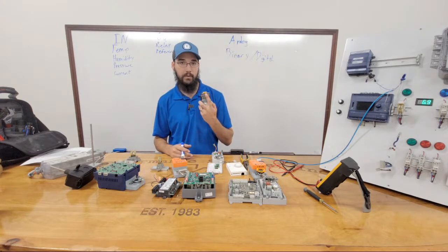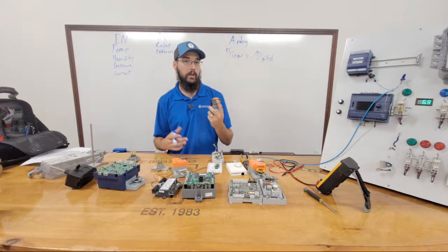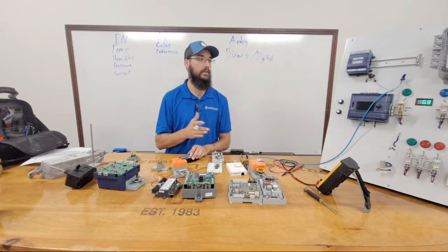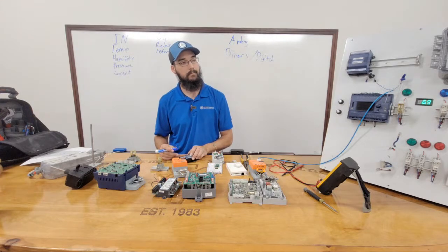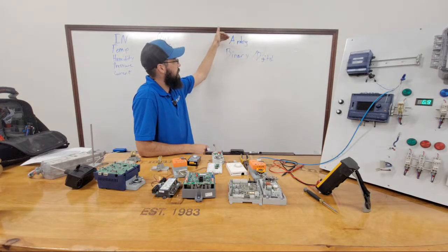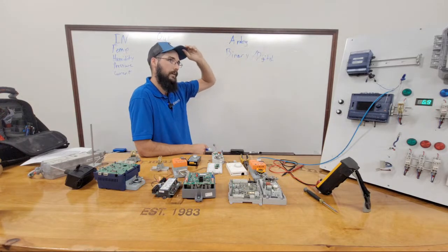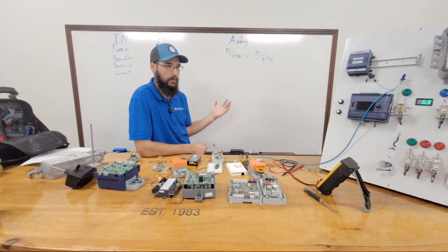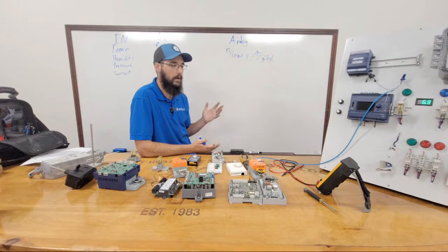So if I then turn around and put that resistor in the circuit in parallel, that 20-something volts would all of a sudden be a 0 to 10 volt somewhere in the middle, and I would be able to see that 0 to 10 ramp up or down. So anyway, those are the two most common. Now transducers, so most of the time if you're working on a transducer on any kind of piece of equipment, those are typically a 0 to 5. So just bear that in mind.